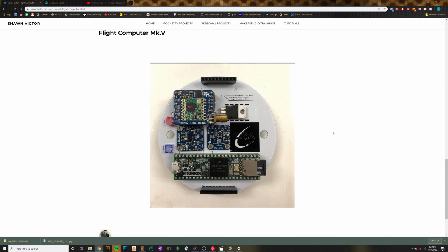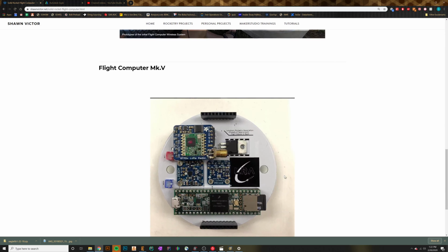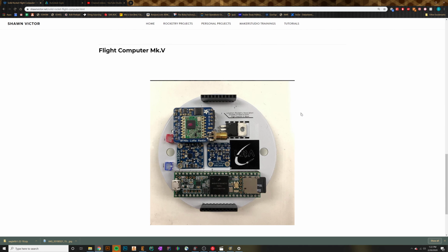Today we'll be talking about how to make custom libraries. These custom libraries are going to help us move from having a breadboard to having something like this. In a breadboard we may have these little sensor boards, like this pressure and temperature sensor board here, that we would normally plug into the breadboard, and then we'd have jumper wires hooked up to something like this, which is our microcontroller. And like I was telling you in that first tutorial, when you have a bunch of jumper cables, there's a lot of room for things to get disconnected, and it's kind of hard to test your platform pretty ruggedly if you just have something like a breadboard.